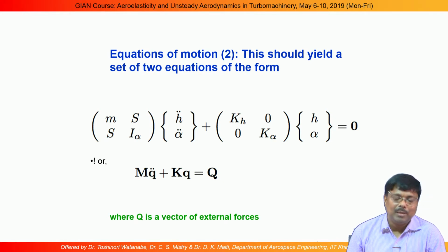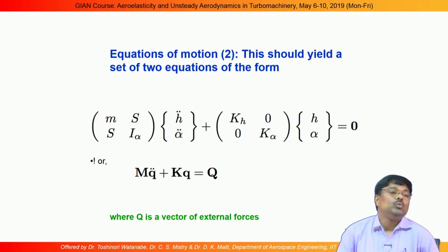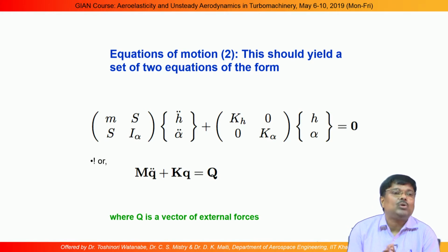Usually we will be extracting complex eigenvalues in the flutter analysis, but not in normal mode analysis. But I will explain to you why normal mode analysis is important, because when we are calculating the aerodynamic load, we need a deformed shape of the structure. Okay. Because when I am calculating the unsteady aerodynamic load, I am considering that it is vibrating in a particular mode.